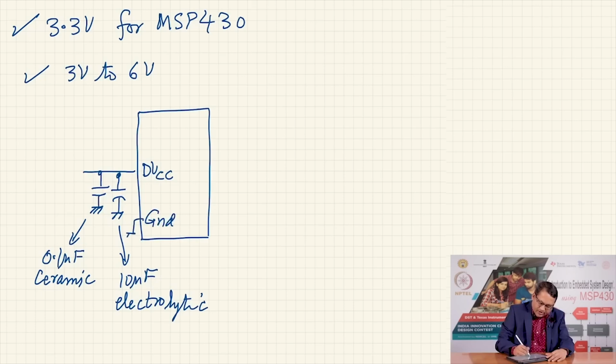So, I ground that pin, and if you have analog AVCC also you would connect a capacitor, two capacitors actually, and please note that I am actually using different grounding symbols to indicate that these do not share the same ground with the ground of the digital part.